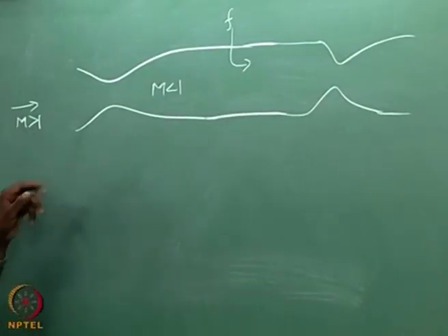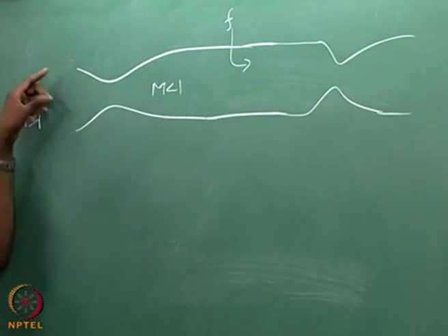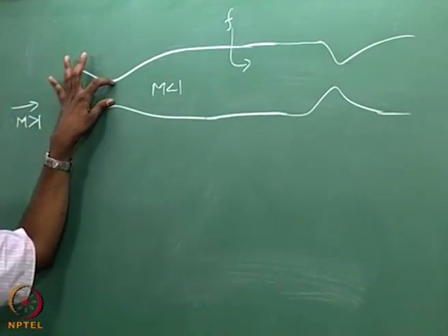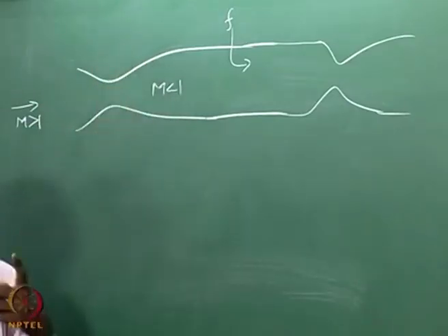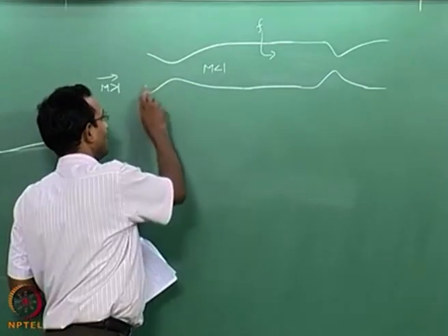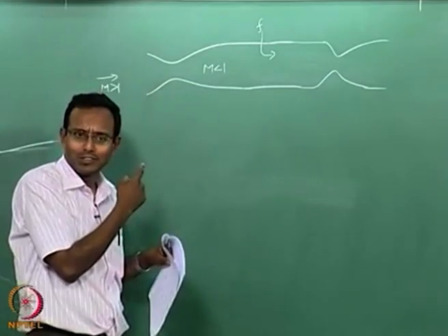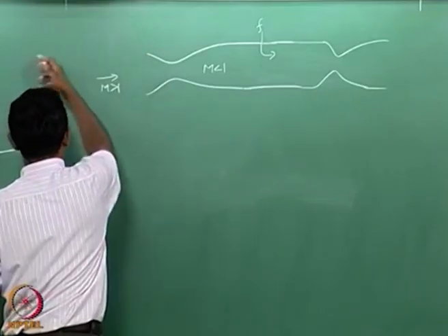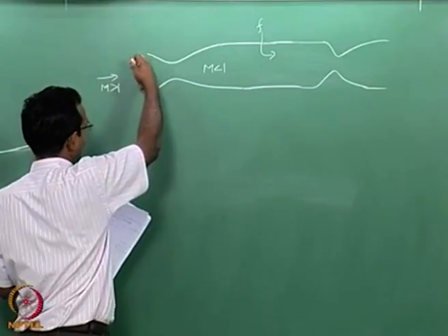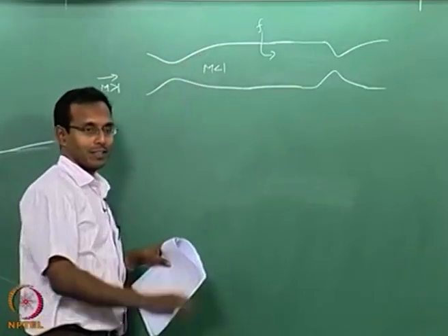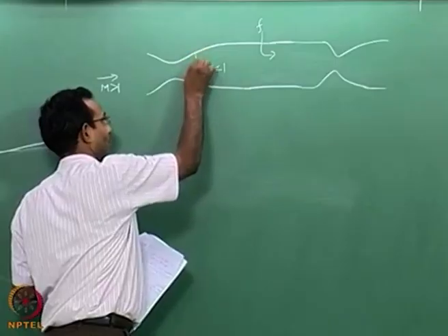I am thinking about there is incoming supersonic flow, it is going to have choking here and it is going to go to subsonic solution. Of course, you should remember your nozzle flow conditions and you should think about if there is, this is a double throat nozzle we discussed some time back. This is like, imagine there is one more duct here and there is a nozzle which made it supersonic flow, it goes through a second throat and it is going subsonic. If that is the case, it is as if shock is sitting here.